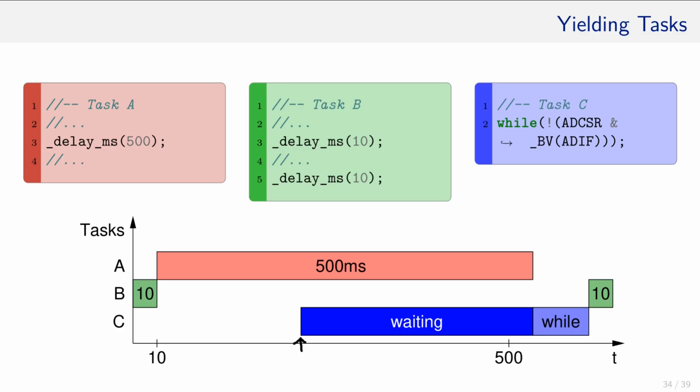Here, the problem is that the scheduler follows a strict cooperative policy and the tasks would like to cooperate. However, function calls will not let them. Obviously, a software developer can dive into the source code of the AVR library and adapt the delay function to the new needs. That makes the source code dependent of the scheduler. Let's see if preemptive scheduling is much better. At least it has the option to interrupt the delay MS functions.